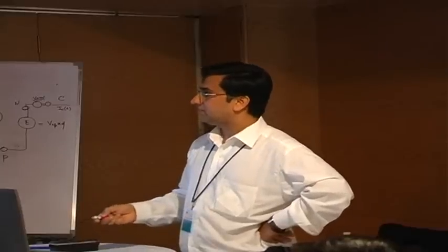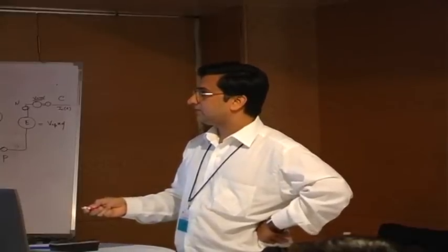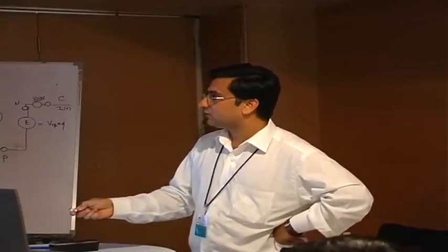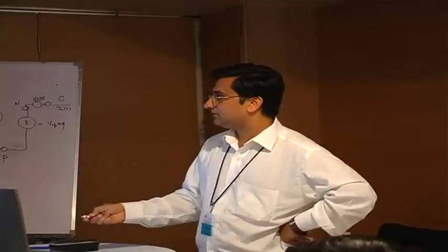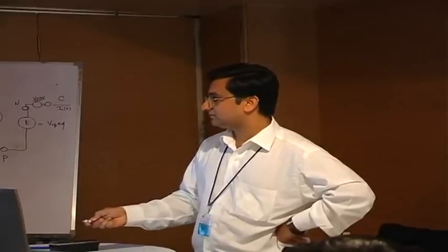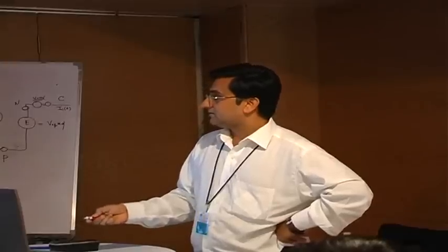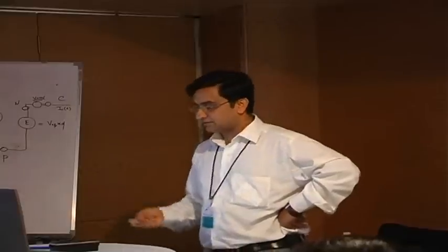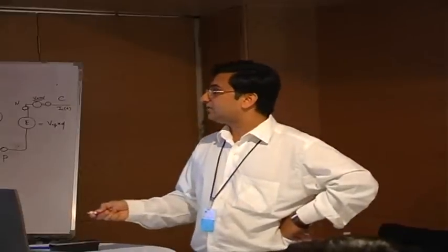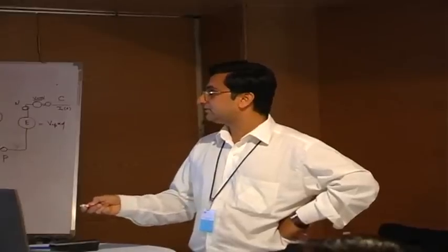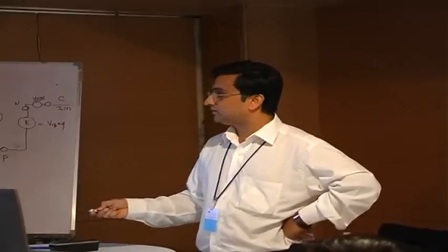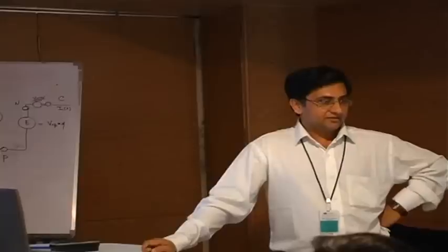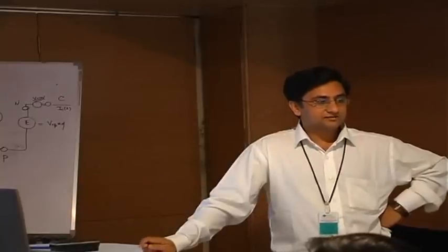So this is an IGBT inverter design. If you see here, this is where the thermal is connected. This is now the Simplorer domain. So here if you see, the thermal domain is hooked here in the circuit domain, and this is an FE domain that is hooked again in the circuit simulation. This is a transient analysis. Every time step it will go here, come back, see the conditions, see here conditions, and load, and then generate the plots. So it takes a lot of time for the simulation result to come out. Alright, it will take time, but you will get the correct result.